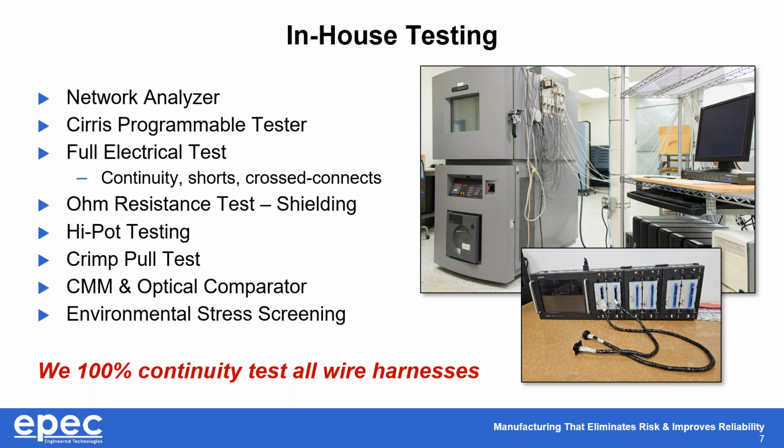High pot testing is one concern we all have, especially when we're dealing with high pin count or a high density connector. Anytime we're doing a high pot test with more than a dozen or two dozen connections, that testing can take hours if not days doing it by hand. Our automated test stations here can do every combination of high pot testing around all the adjacent pins, which is very common in military and aerospace type applications.